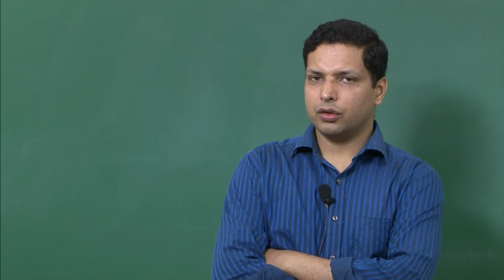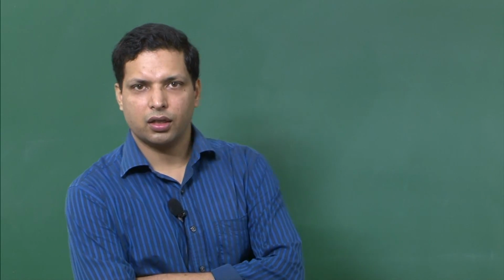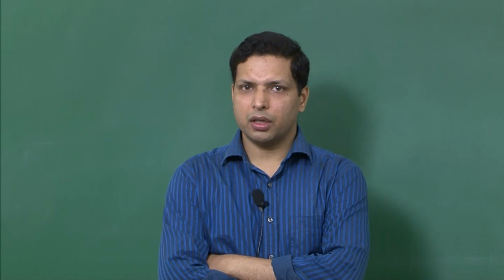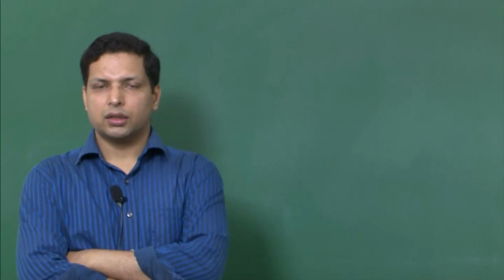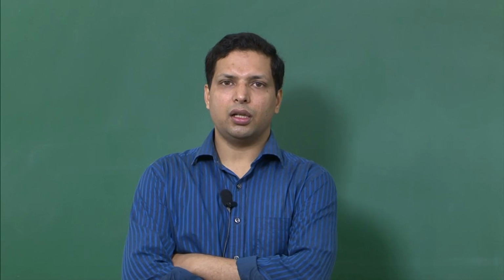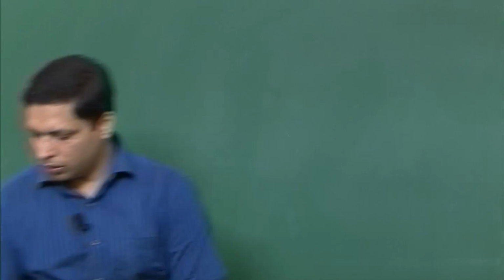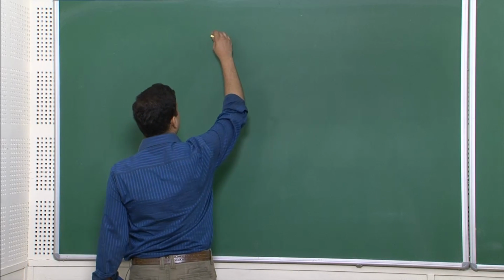Good morning friends. So, we were discussing the composition variation during solidification. We looked at one very simple case, which was the equilibrium condition where everything is under equilibrium, and then we started looking at the other case where we have no solid diffusion, but still full homogenization or full mixing in the liquid. So, we found that there is an equation. First let me write what the title is.